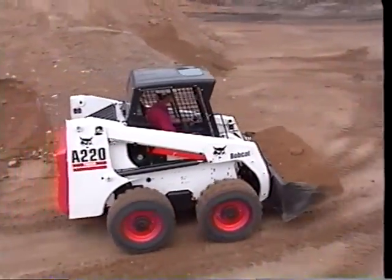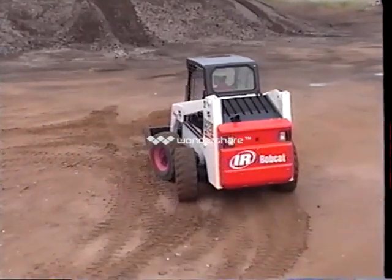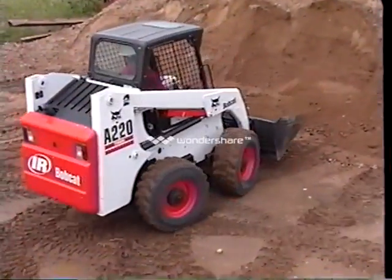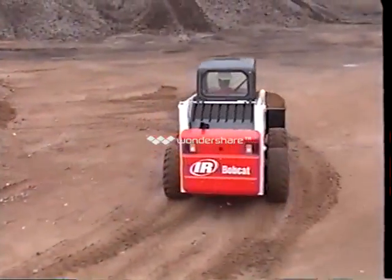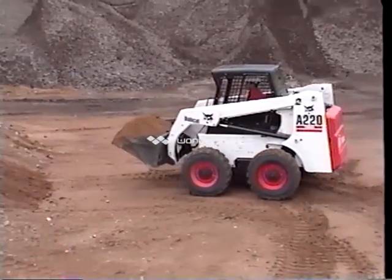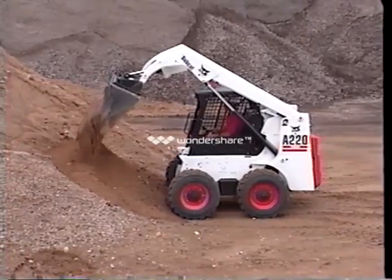In all-wheel steer mode, the front wheels angle in the direction the left joystick is moved, and the rear wheels angle in the opposite direction. The front and rear wheels follow in the same path and turn the loader in a gradual circle. In skid steer mode, the loader's wheels always remain aligned straight ahead during loader operation, and the wheels rotate in opposite directions to skid steer the loader.